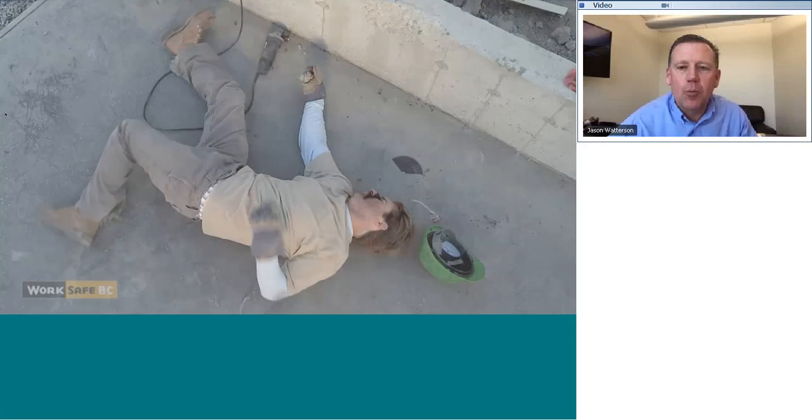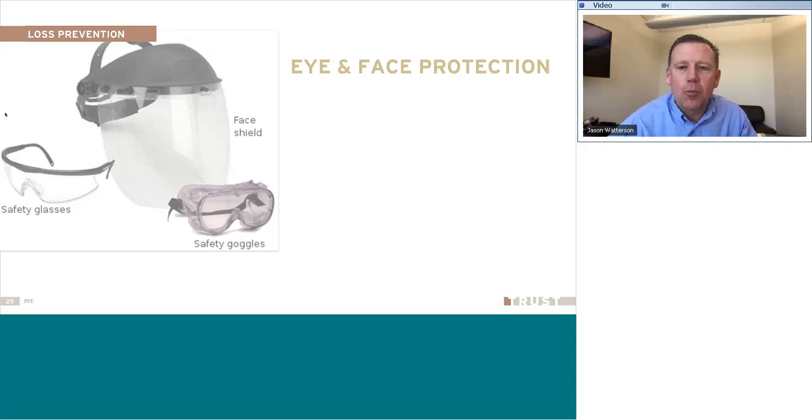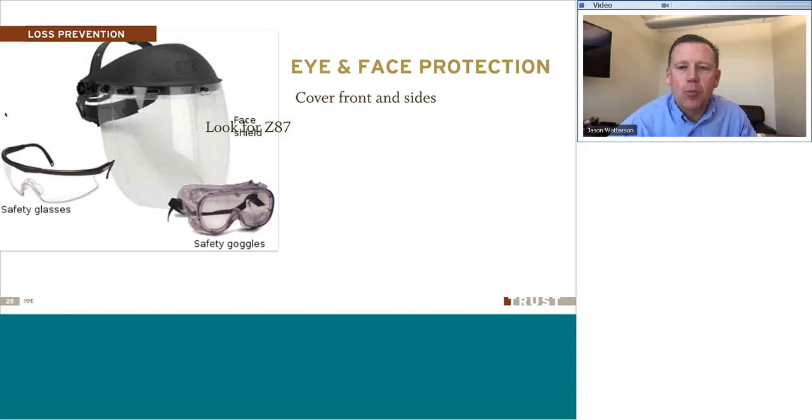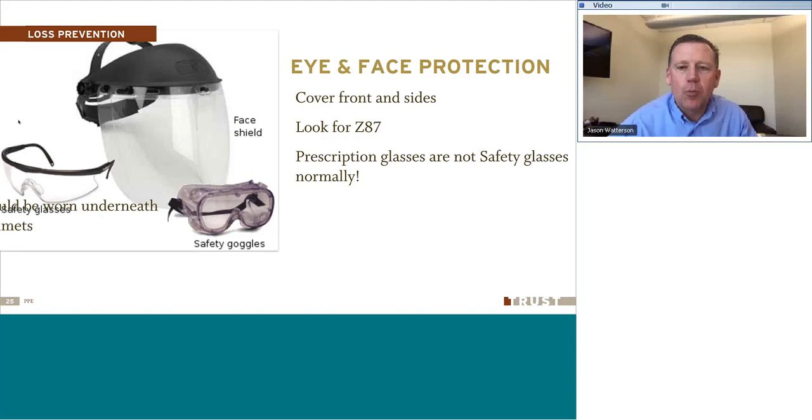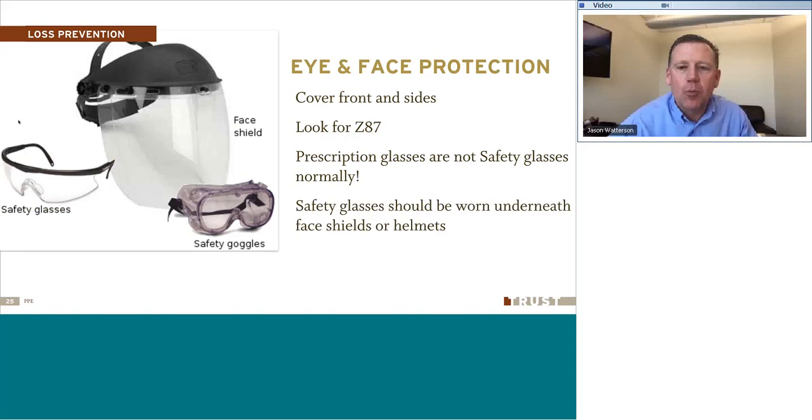And here's a sample just with a die grinder or an angle grinder where that wheel broke apart and actually penetrated the face shield and touched the person's face as it penetrated, but didn't cause any injury. You can just imagine how serious that would have been without that piece of personal protective equipment. Let's not improvise like this guy. Let's use the appropriate equipment at the right time.